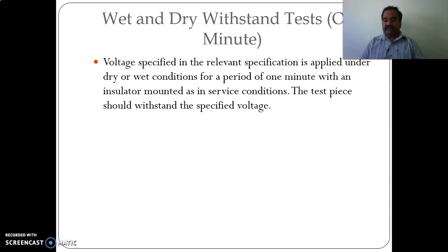So, after application of voltage till the completion of 1 minute, if the insulator has not experienced any damage or flashover or puncture, then the insulator is supposed to have passed the test. So, it is to be repeated in both wet and dry conditions and the same must be recorded. So, wet and dry withstand tests for 1 minute.